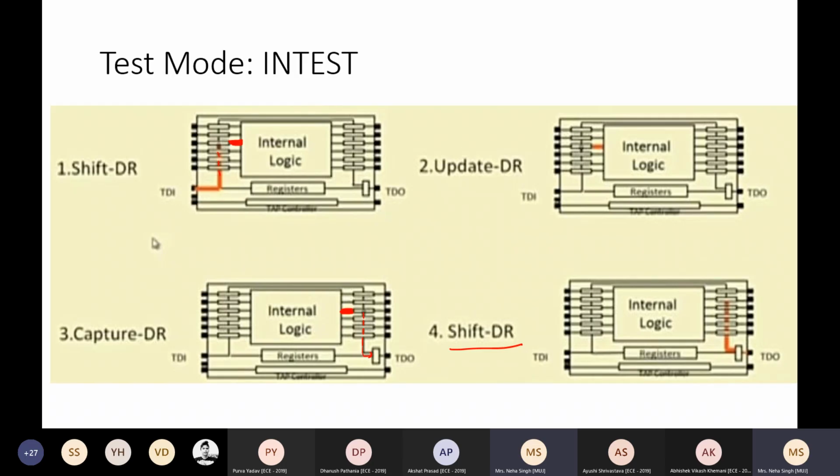Extra pins की जरूरत नहीं पड़ेगी. Otherwise, if each IC needs to have multiple pins, we can have 64 pins on one side at least. So 64 into 4, that many pins should be available. इतने तो मेरे primary inputs ही हो जाते हैं, input and output. So it is now a question mark where to have those testing pins. So in order to avoid that, we use these wrappers so that no extra pins will be required on the IC for testing purposes. However, there are certain built-in test mechanisms which may be present in those ICs, but we'll deal with those a bit later.